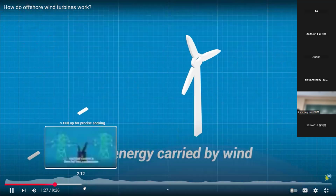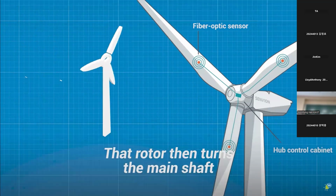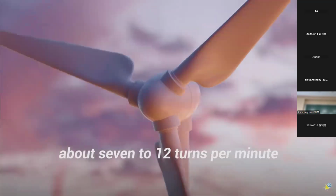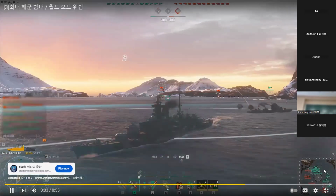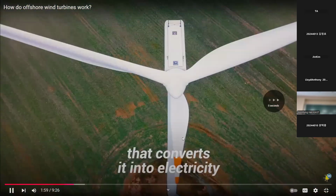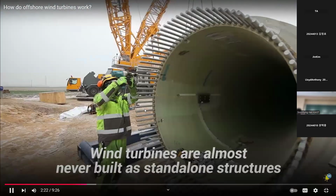Onshore and offshore are pretty much the same. The energy carried by wind turns 2 or 3 propeller-like blades around a rotor. That rotor then turns the main shaft. This low-speed shaft spins at the same speed as the blades, about 7 to 12 turns per minute. A gearbox boosts speed. Here's where things get interesting. Wind turbines are almost never built as standalone structures.